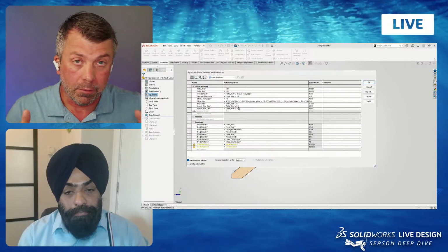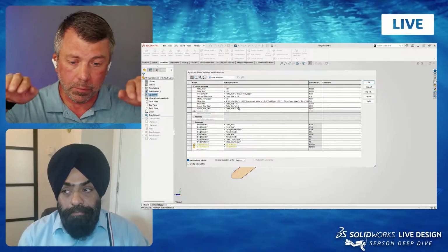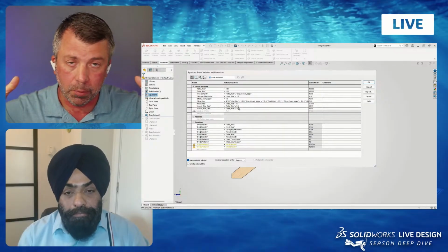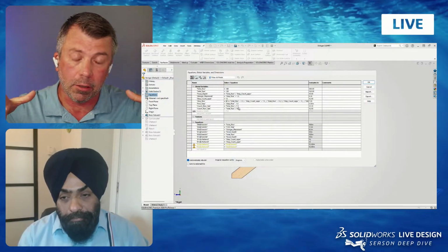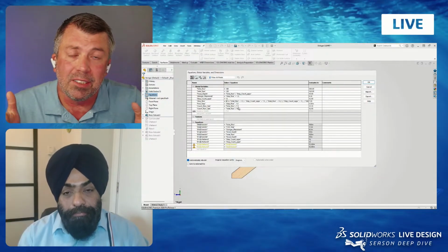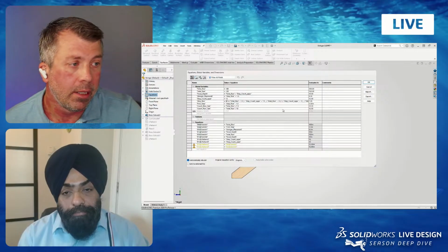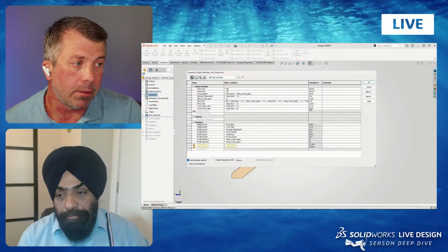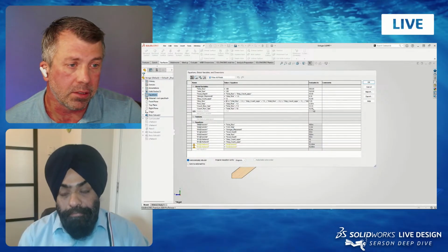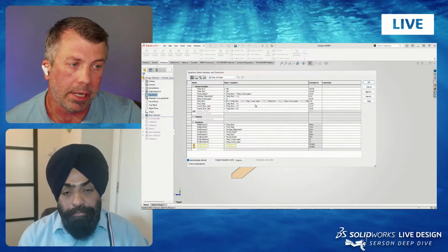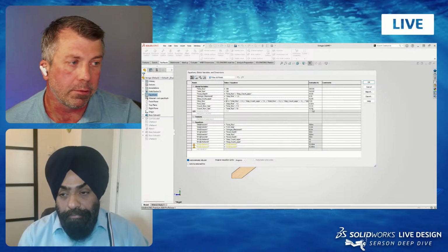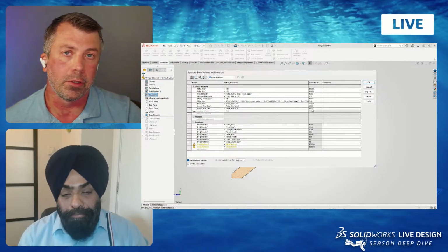The total run of the step is based on two 2x6s or one 2x12 that is going to sit on as the actual stair tread on top. So I said, let's make it 10 inches. And over here, this is telling me 13.33. This is the count of steps if we abide by that, so I'm going to have either 12 stairs or 13 stairs.